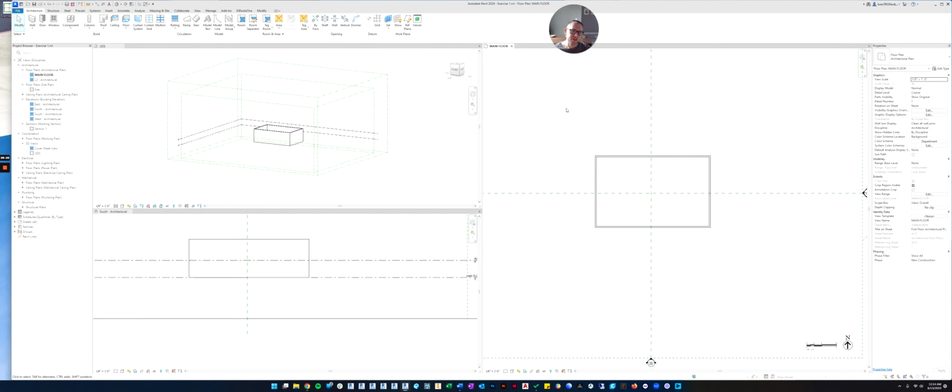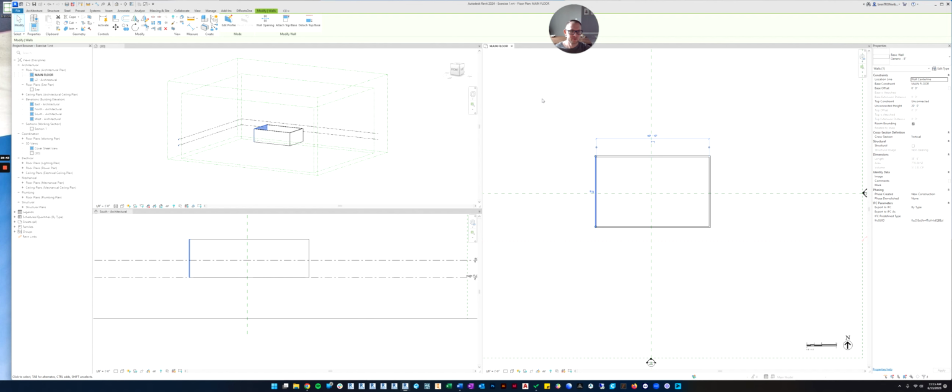The other way is if you click and then drag your mouse, it makes this box, and anything within the box will get selected. So do you see how all 4 walls are selected? Or if I only completely enclose one wall, it just selects the one wall. So I can get all 4, or I can just get 1.